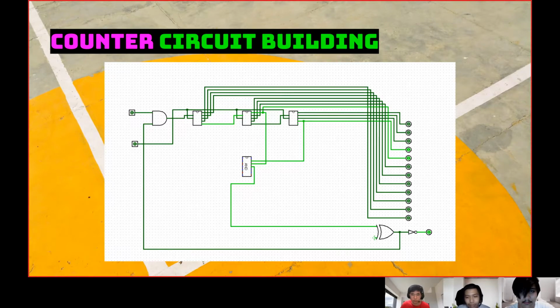The first 4-bit outputs on top are all sent into the hundreds position. The next four are the tens, and then the last four are the ones bits. And that final output, as you can see at the bottom, connected to the XOR gate, is actually the enable signal that will be used for the PIPO and the counter display. So it will properly display only after the timer has hit 180. And so, next slide, please.